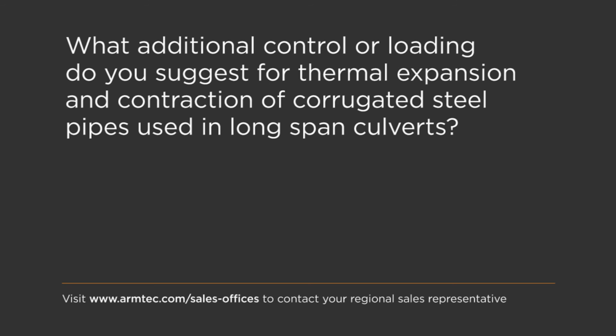Right, so generally we have very stringent requirements for backfilling, especially in winter conditions. The soil has to have certain properties. It has to be well-graded, free-draining material that can be compacted to at least 95% standard Proctor density. So the soil has to adhere to these specifications that we detail on our drawings, and as such, winter construction can be tricky, but there are ways to ensure that there are no frozen materials anywhere in the backfill material. So that all has to be removed prior to backfilling, as well as techniques to heat and tarp the backfill to make sure that none of the issues arise with frozen material.